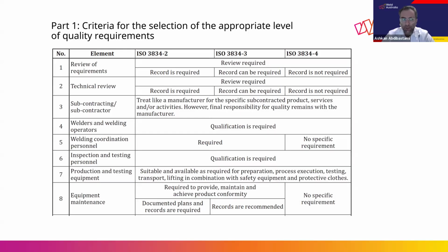And the checklist needs to capture all the details extracted from different documents. For example, if the welding standard is AS/NZS 1554 part 1, for structural purposes, you need to specify that in the checklist. And anything else with respect to the parent material, joint preparation, and so on. So this table from part 1 is a very useful reference to know what we need to prepare and what we need to provide during the audit.